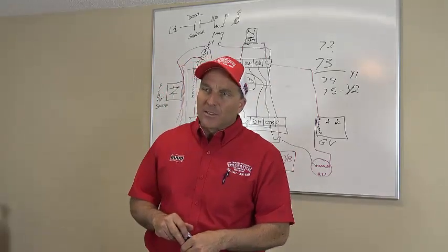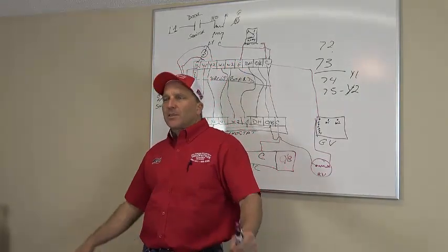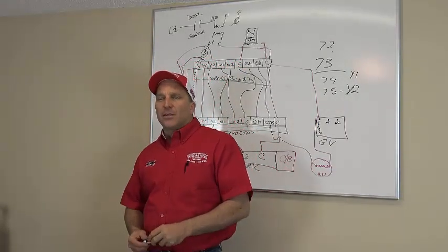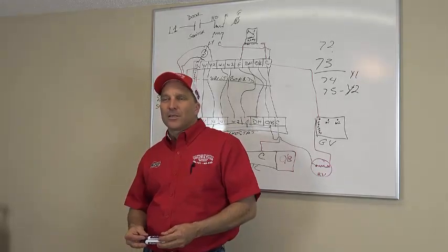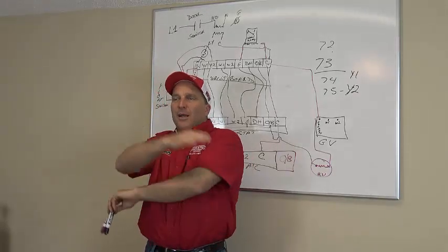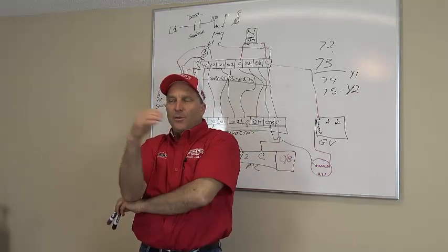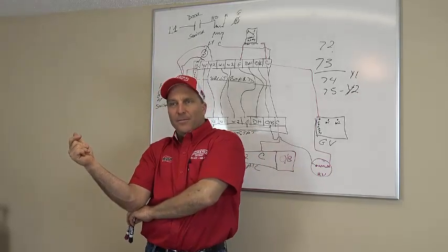So a heat pump runs and you get a big block of ice outside and the customer's calling up going, my outdoor unit's got a big block of ice on it. How can you actually defrost that? Run fan. Tell them to run the air conditioning. Turn the air conditioning system on for 10 minutes and it will actually reverse the refrigerant back again, and your air conditioning's running and you've got hot gas running through your condenser and it will melt that ice like that. Okay?